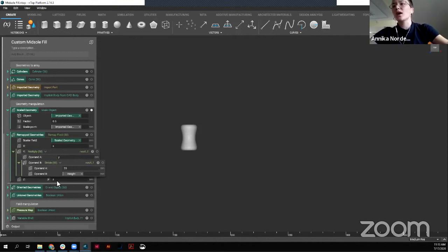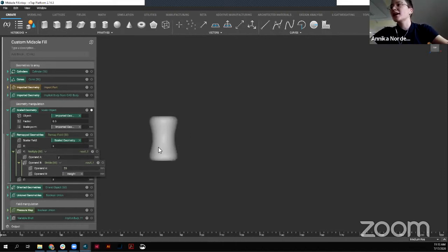And so really what I'm doing is just scaling this geometry just along the Y axis. So my X and my Z, I want to keep constant, right? Because as I said, I want to keep this constant diameter here. However, I want to change that Y. I want to push and pull it. So you see I have this 25 value. That's because I know the height of this geometry is 25 millimeters. And so I'm dividing that by height.